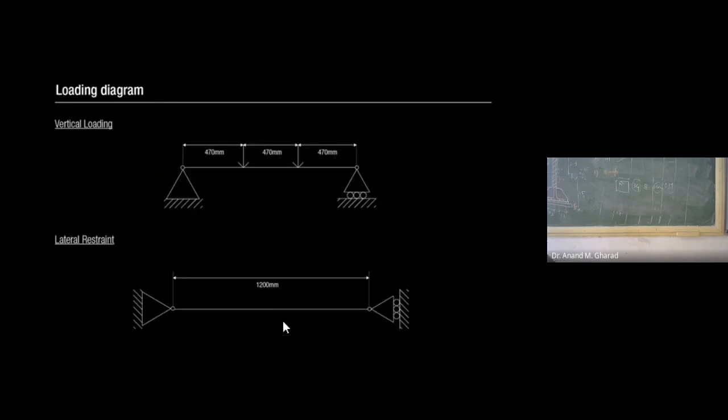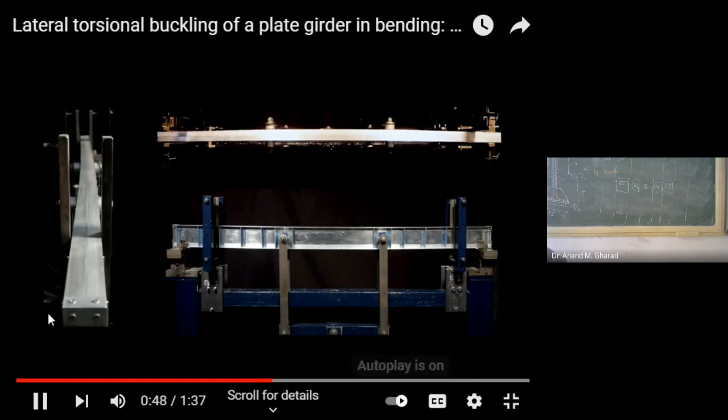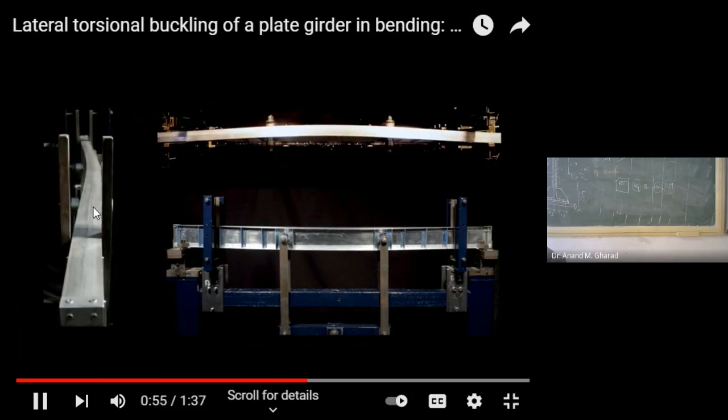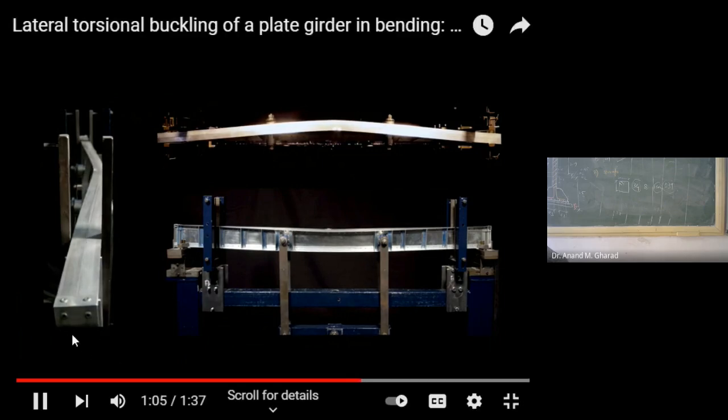Now you will appreciate that only vertical loads are provided. No lateral force is acting, even though the beam gets deflected in the lateral direction. And not only in the lateral direction, but you will see that it gets twisted. देखो, vertical direction में loading लग रहा है, and slowly this beam is getting deflected. Now just observe carefully. ये वाला section देखो, load बढ़ रहा है, and what do you observe? See, ये देखो, ये direction में वो deflect हुआ है. Vertical direction में loading है, लेकिन deflect इस direction और perpendicular direction पर, that is buckling. And in addition to buckling, ये जो cross section है, ये देखो, ये twist हो चुका है.